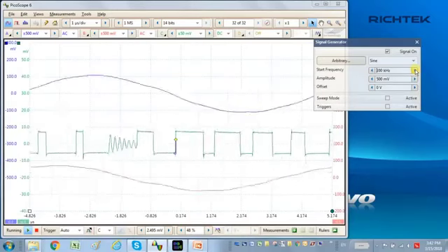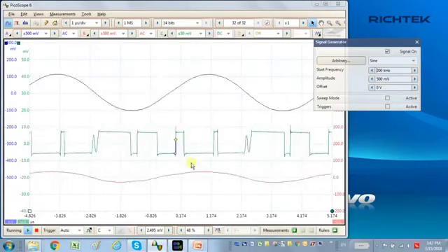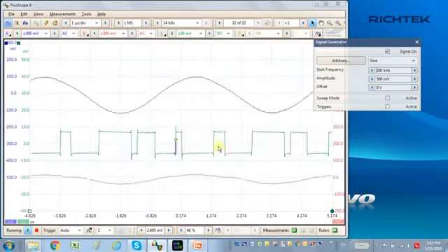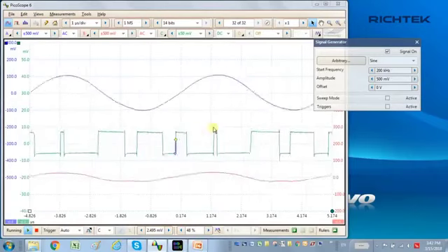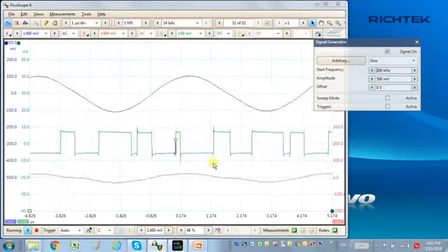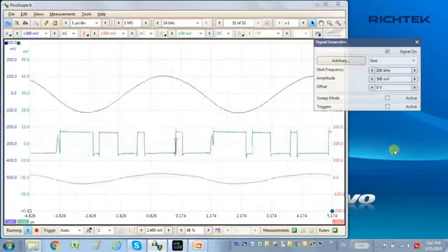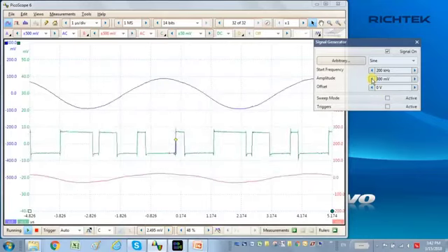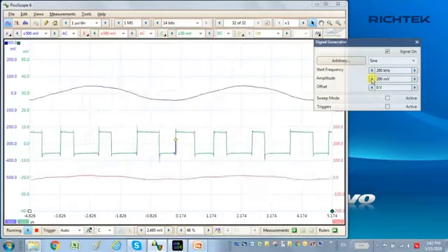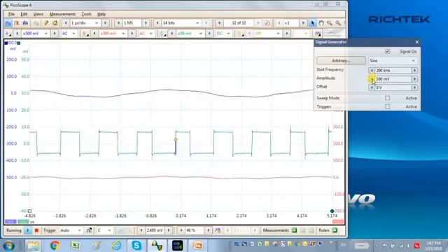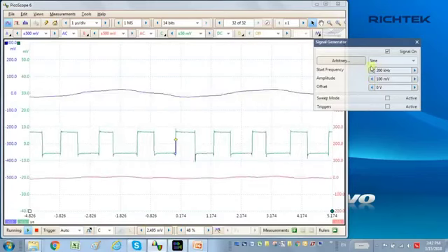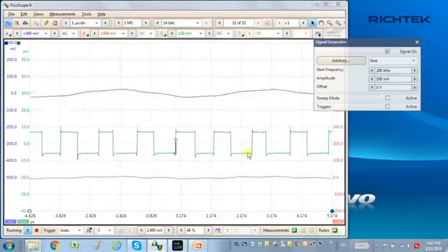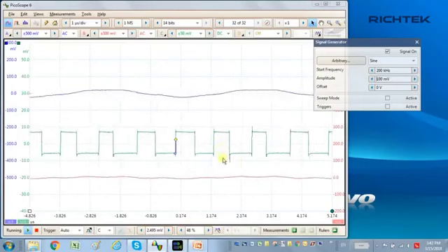At 200 kHz injection frequency, you can now see that the switching signal duty cycle shows extreme fluctuations, hitting minimum and maximum duty cycle limits, and at some points the converter even goes into discontinuous mode. For accurate gain phase measurement results, the converter operation must stay within its linear operation range over the entire sweep frequency range, and should not switch from one operation mode to another. To accomplish this, reduce the injection signal amplitude to keep the worst-case duty cycle variation at moderate levels.